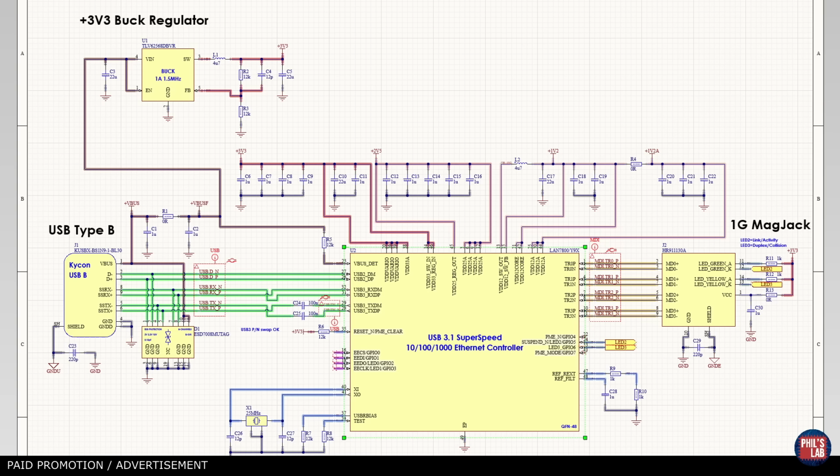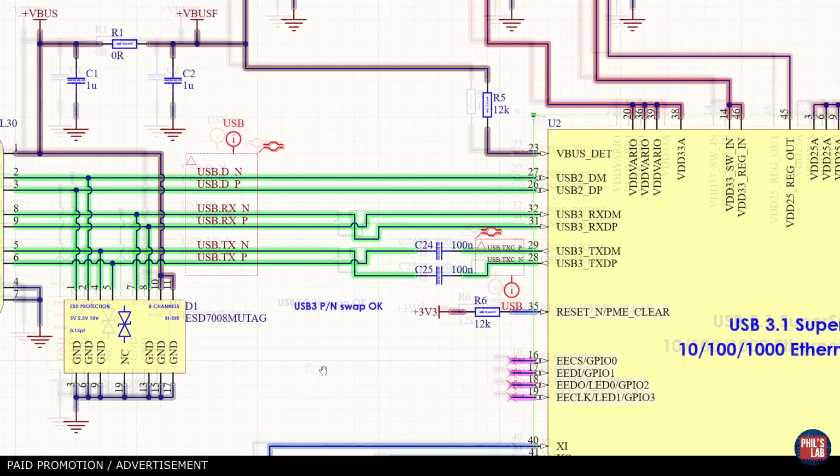When you're about to perform any type of simulation, I'd strongly suggest naming all of your nets in your schematic. This will make it far easier then to find the relevant nets you would like to simulate, be that for DC or AC power analysis or for signal integrity analysis, or for instance high-speed nets. This is my typical practice, and what I do for every single schematic that I design is that every single net gets its own net label.